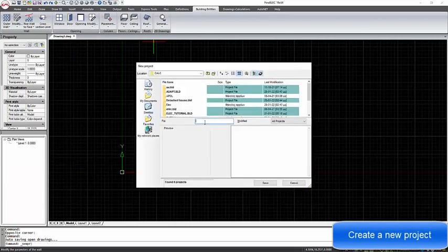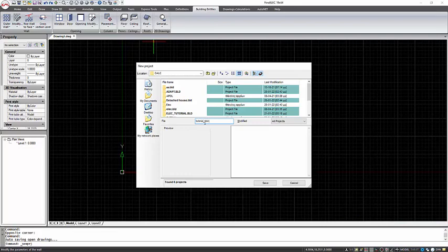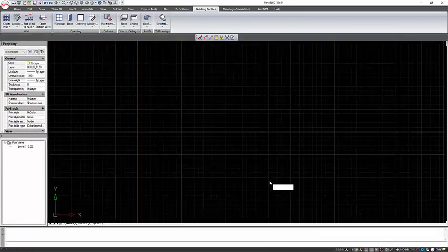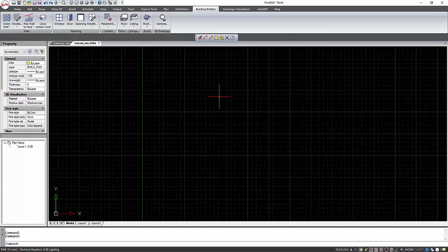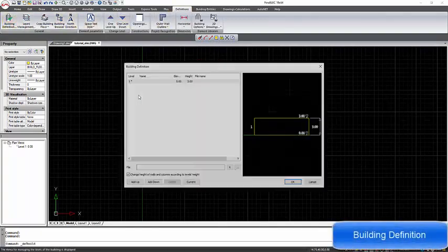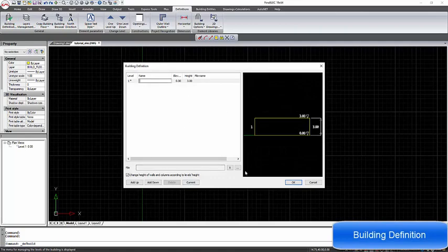First of all, a new project is created by giving its name. When we create a new project, a folder with the BLD format is created, and inside that folder, the DWG format drawing is placed. The folder and the drawing share the same name of the project. If we have some architectural designs, we can place them as external references.